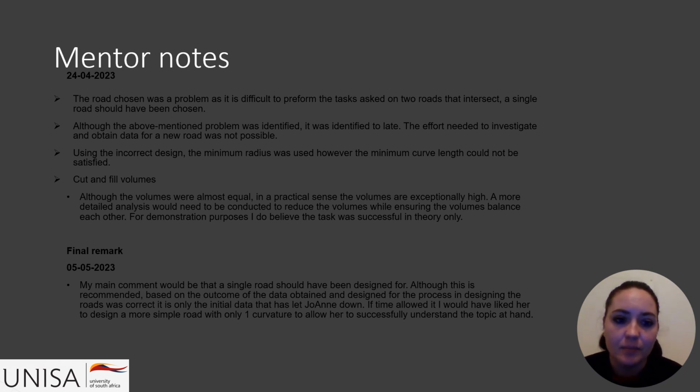The cut and fill volumes, yes, they did work out, or they did equal. However, he pointed out that it's impractical to have such a high value, and that instead of focusing on the slope of the road, I should have focused more on going with the natural ground level in order to save costs and labor costs and for practicality, as the amount of effort needed to excavate the material and then place it somewhere else would be infeasible.